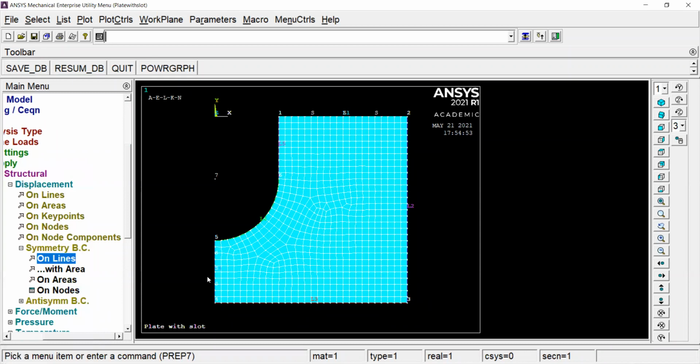These S's tell us that there is a symmetrical boundary condition at this point and at this point. So we have successfully modeled a quarter of a full-on plate and essentially cut down our processing time by a quarter, down by 3/4 of what it would have been if we modeled the whole plate.